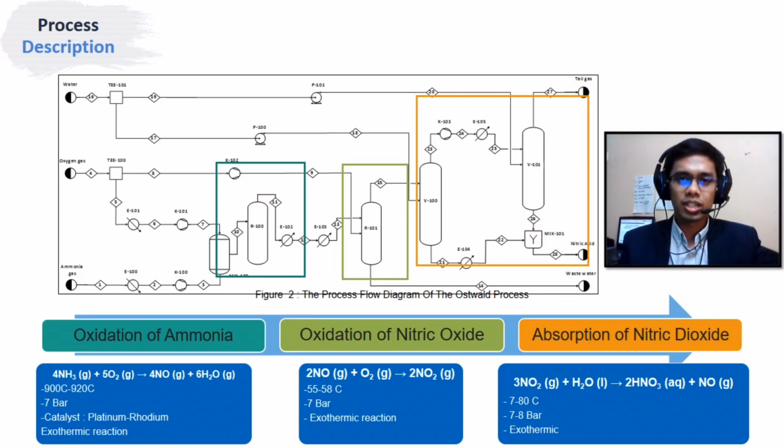For this production, it has been proposed to produce nitric acid by oxidation of ammonia on a platinum and rhodium catalyst, as it offers more ecological advantages than other methods. Ammonia and compressed air are fed into the inlet stream for mixing before being heated to 900 degrees Celsius in a catalytic converter reactor to form nitric oxide.